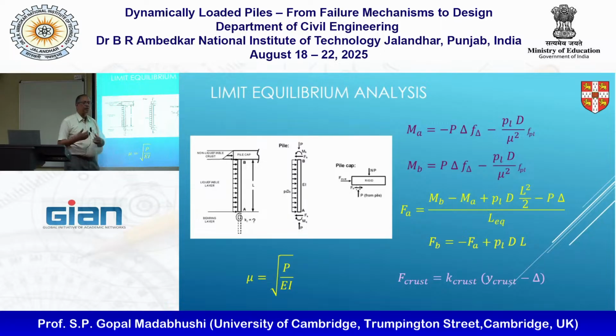This is almost telling us what the applied load P is relative to its flexural stiffness. If you plug in the mu's, it will become fairly obvious. It's going to come down to the P delta effect there as well.